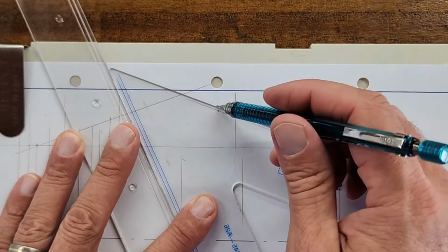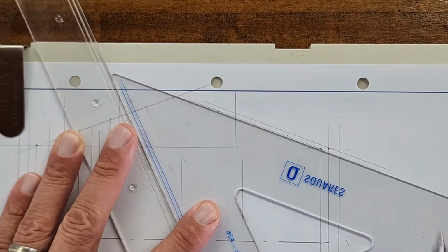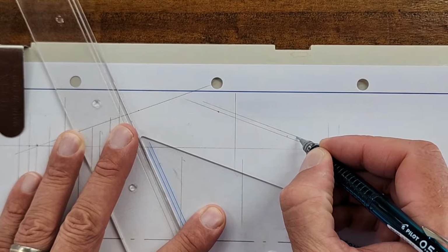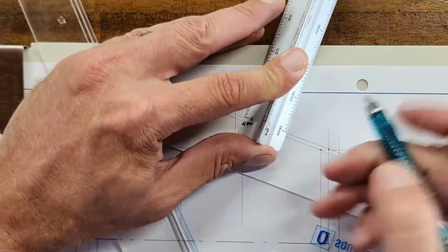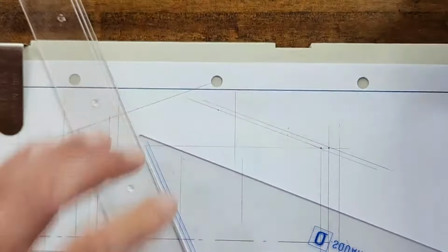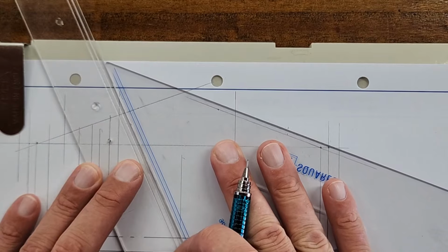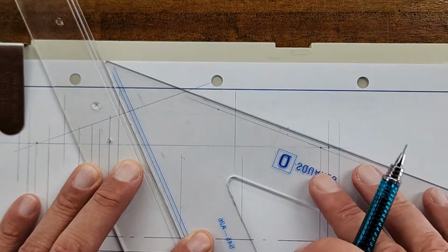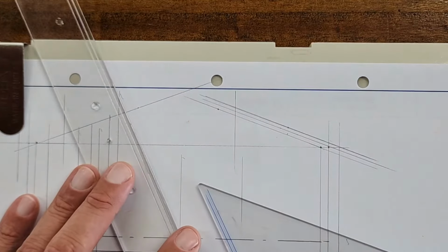So there's the roof truss running. Then what goes on top of that? The purlins. And that purlin is a 75 by 50. And then there's a corrugated iron sheet on top of that. So we're just doing the spacing here to get our spacing right. And then there's our top of the roof truss, okay?